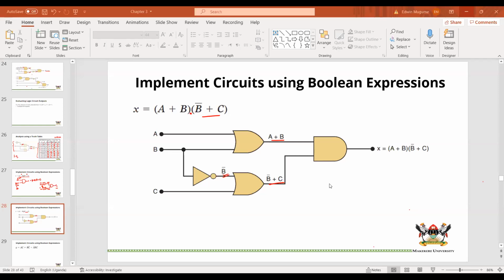But for those of you who did, you can see how different the answers are. Okay, this is why we do quizzes, because if everyone was getting the same answer, then I would understand, but clearly here, there is an issue. If you add odd parity here in number 1, you already have 4 ones. If you add odd parity, you add a 1, meaning that you're making them 5 ones. The question is, where do you add that 1? You add it at the left-hand side. So the parity bit is always the most significant bit. And so people who chose number 1 got it correct. You can see there are 14 people, 28 people, and 12 people who have got it wrong.